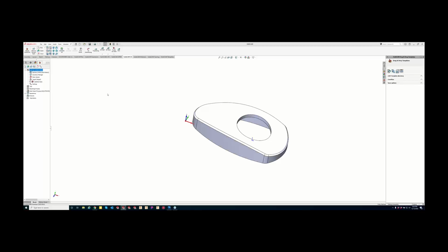Well, now today we're going to be showing linear, and linear is going to be the exact opposite of the Constant Z. So it's based off of a step over versus a step down. Where that really comes in handy for you guys is on a more flat area. So like we said, 0 to 45 degrees.